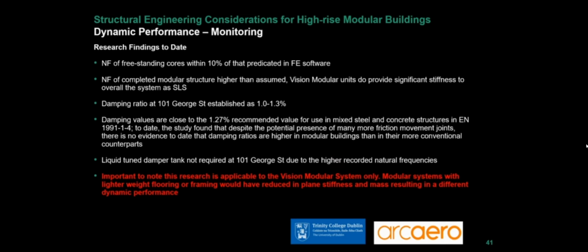But at 101 George Street, we ended up not needing the liquid tuned damper tank because the frequencies were significantly high enough to not need the tank. And even with the very conservative assumptions, we were right on the borderline with the accelerations anyway. So that was a good result, that we were able to remove that and prove the system works.